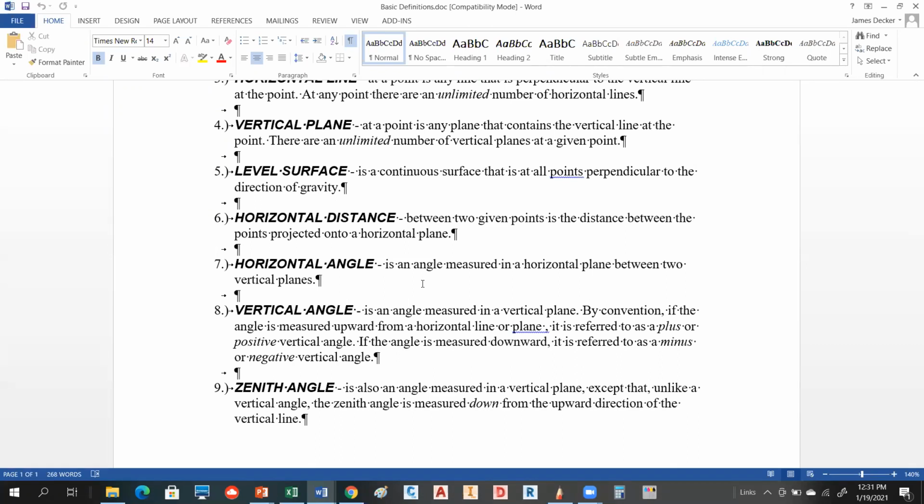Most of you probably have taken that measurements class, and they constantly told you to level your instrument when you turn angles. The reason is if you don't, your protractor is not horizontal, so it's giving you a skewed angle. Okay? Horizontal angles will be very important. The horizontal angle and the horizontal distance will be used quite often together to give you what's called a position. That's very important.